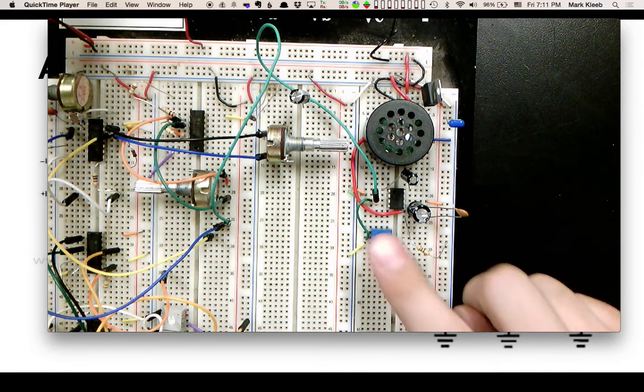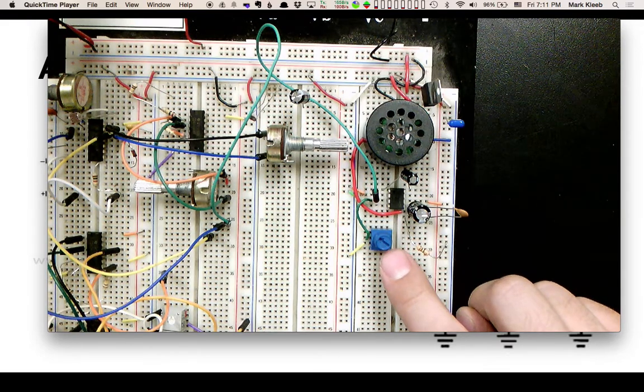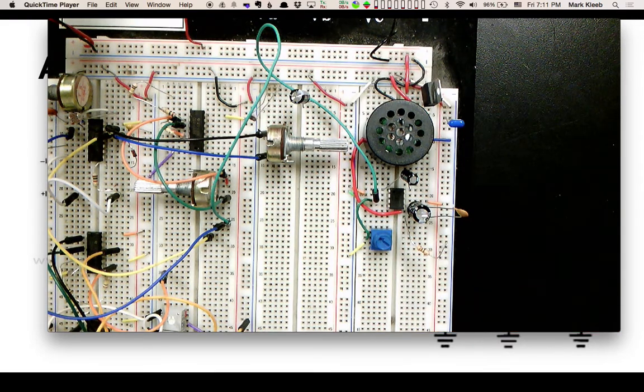I should really be using a logarithmic tapered pot here, and you would know that if you were picking up a potentiometer and you said, okay, I need a 10K potentiometer. If it's labeled with a B, it's a linear. If it's labeled with an A, it is going to be logarithmic. And I just always think like A for audio is the way to remember that. Okay, so